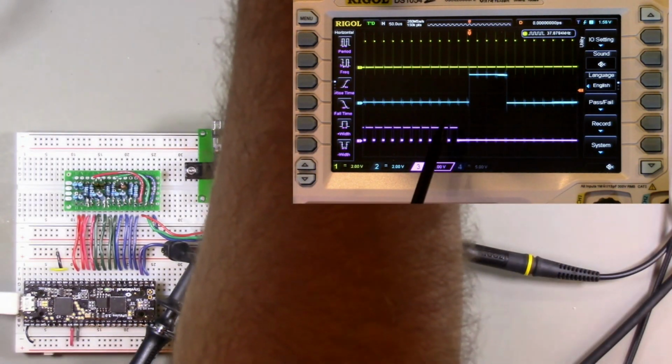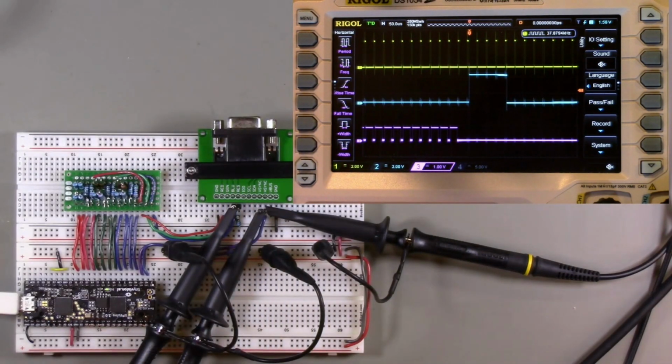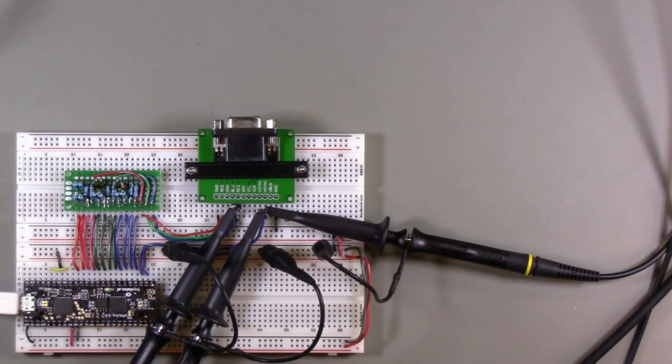So I would say at this point, this looks quite promising. I think this is more or less what we are expecting to see. So at this point, I think we are ready to try this on an actual VGA monitor. One thing I should mention is that these VSync and HSync signals are 5-volt TTL signals, so we can directly connect the 3.3 volt outputs of the FPGA to those inputs on the monitor. We don't need to do any kind of level conversion or attenuation.